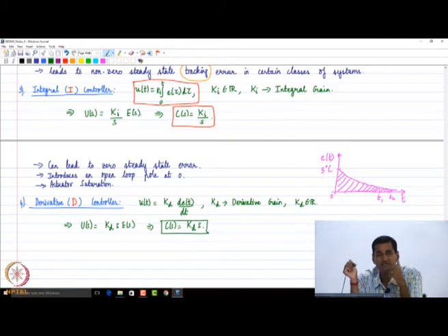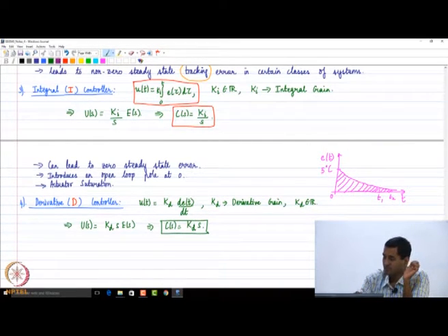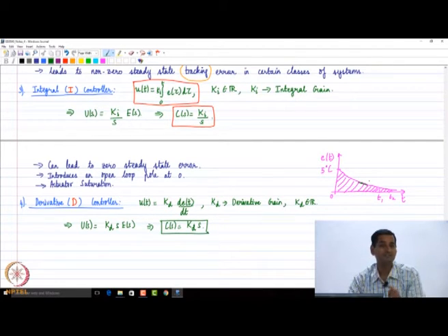But physically, what does the derivative controller do? The error is going to change more in the future, so it will do a higher correction. Okay, very good. If you look at the derivative action itself, let's say you take any time t. The derivative is going to calculate the slope of the error. So in a certain sense, it's peeking into the future.